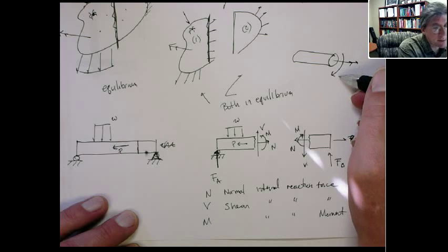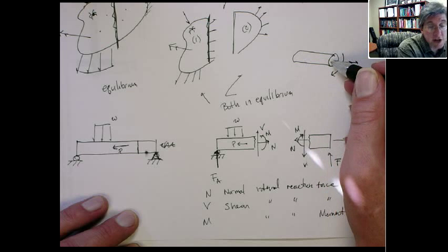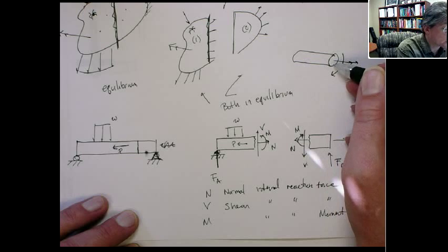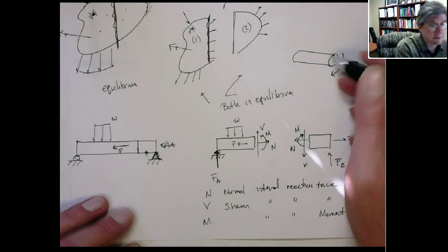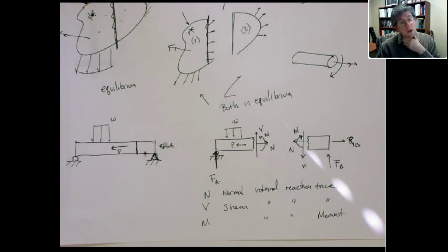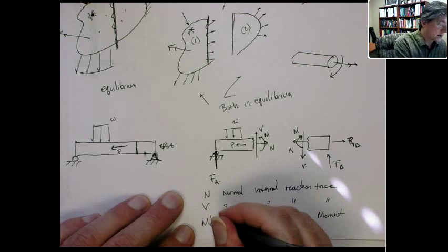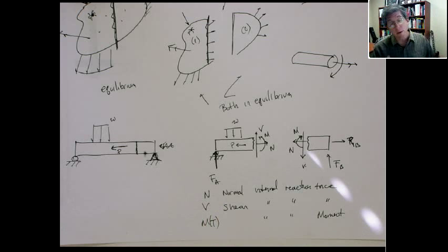But we consider this to be more like a torque because this looks more like a shaft or torsional element, and linguistically we call that a torque. Although from a mechanics standpoint, they really are the same. In fact, I usually stick with moment. Okay, you can think of torque as a subset of moment. Although the book makes a distinction between those.